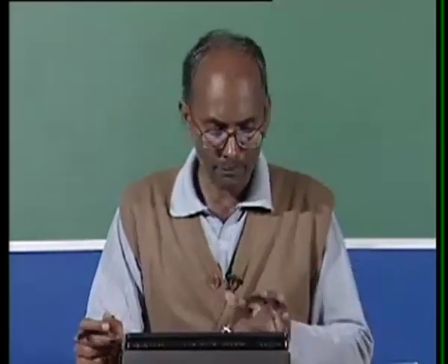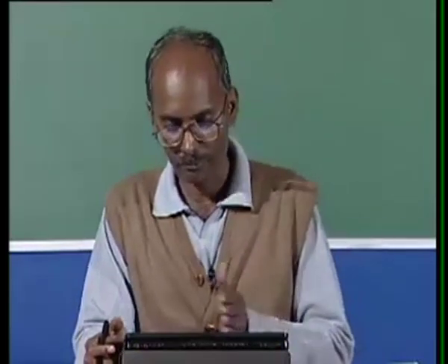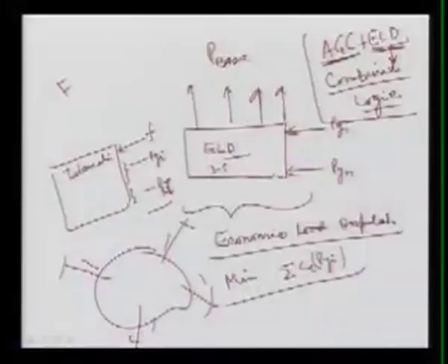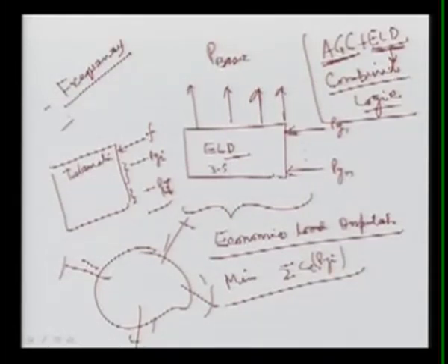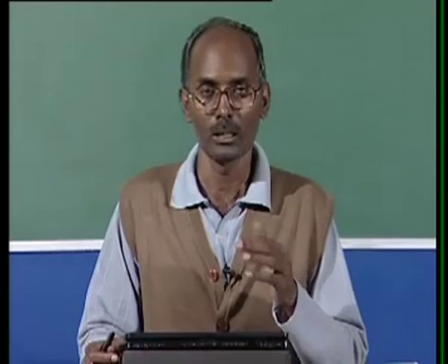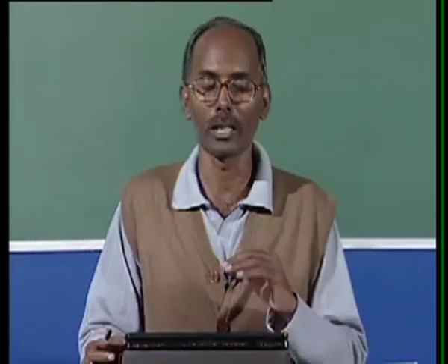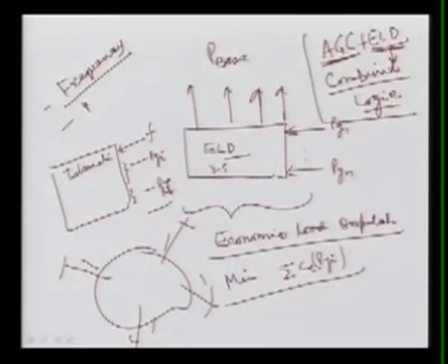So now I can recap what I discussed in these first 6 lectures that was related to your frequency control. In frequency control, we modeled the various components that are related to the frequency calculation of the system, means we model governor, turbine, power system, and then we saw that we require some controller because the frequency error due to certain disturbances, change in the loadings in that area, is not 0. Then we proposed our PI integral controller, that is a reset controller for one area.